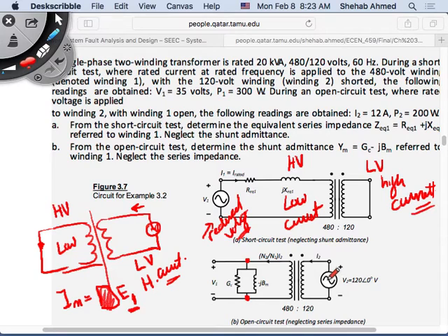So I can buy a low voltage source, put it on my secondary side, which is low voltage, right? Put it on the secondary side, conduct my test. If I put voltage here, again, I'm only pushing a very small amount of current, right? It's only magnetizing current that's flowing, not the full current, because this is an open circuit on this side. In this case, the current will flow through this magnetizing branch, and I have my E voltage now, and I have my magnetizing current, or excitation current, flowing as well. Okay? So any questions on this?